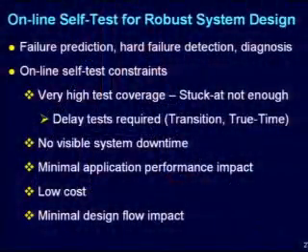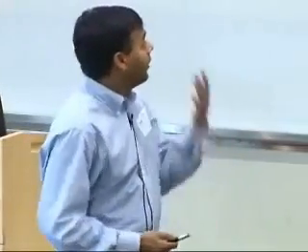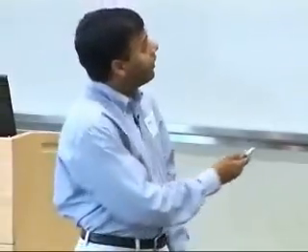Now, as we said, to be able to do a good circuit failure prediction, you have to apply a very thorough online self-test. And why? Because it could very well be that your application may not be exercising the paths that are aging, because it depends on the profiles of your application. And we know for any prediction mechanism, it's garbage in, garbage out. If you do not give good inputs, you're not going to get good prediction. And also, online self-test is useful for hard failure detection and diagnosis.